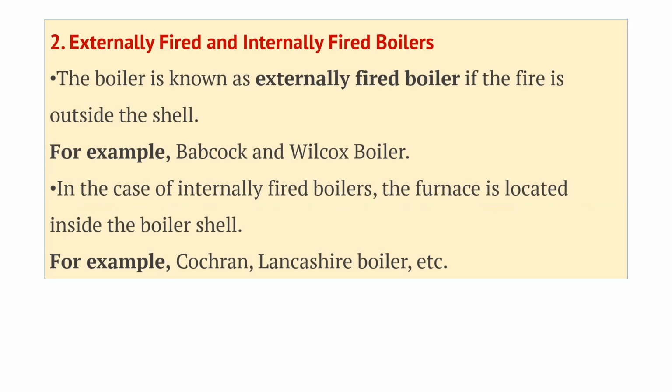Externally fired means the fuel combustion takes place outside the boiler shell or the cylinder. One example is Babcock and Wilcox. And the second variety is internally fired, where the boiler shell itself contains the furnace also. So it is an internally fired boiler. Examples of this are the Cochran boiler and the Lancashire boiler, which I'm going to show in the next lectures.